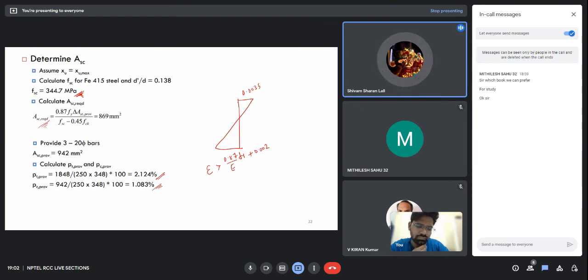And we can have a second case, where the compression strain at the top fiber is 0.0035 and the tensile strain is more than 0.002 plus 0.87 fy over Es. So we can have a greater tensile strain value, and according to that we can create the formula. According to the first case, when we have 0.0035, which is the lesser one, then we can create a stress block according to that also, no?